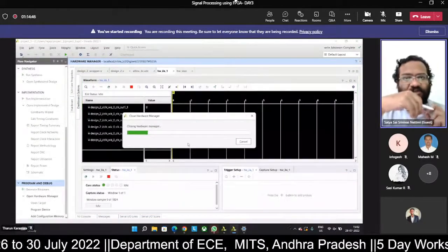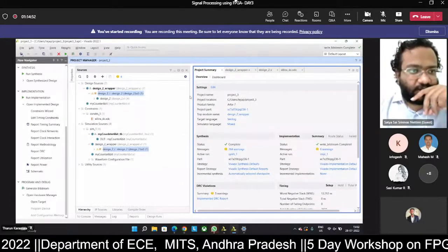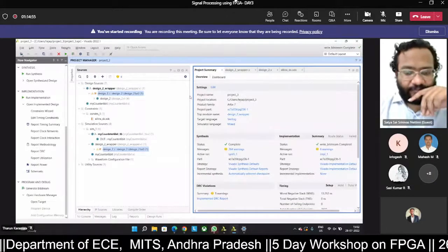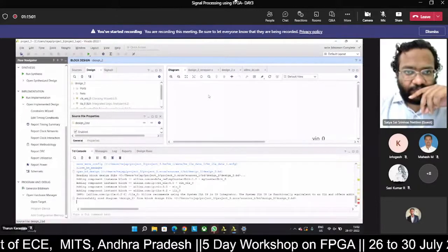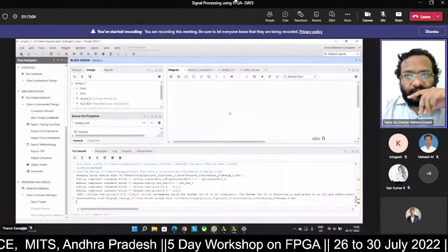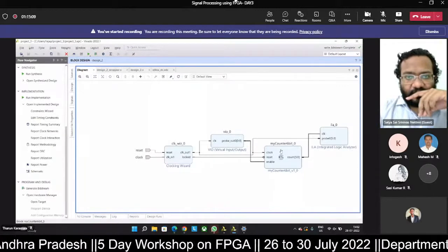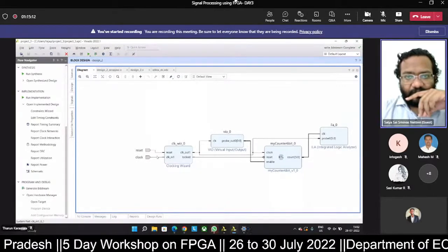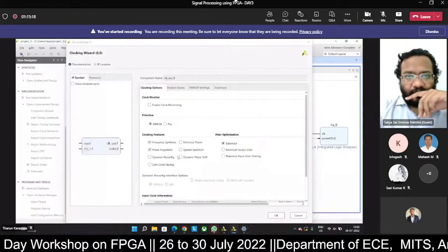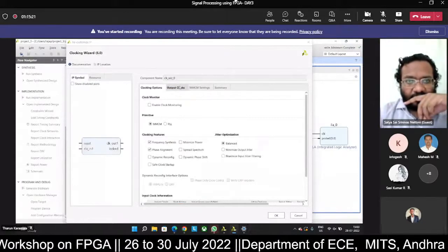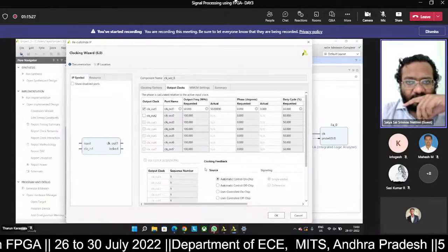Generation of output products is an error, so that is a big problem. Just open the block design. Maximize it, please. Just click on the clocking wizard. Open the customization window. Clocking wizard, yeah. In the IP customization window, go to output clocks. Why is it not...